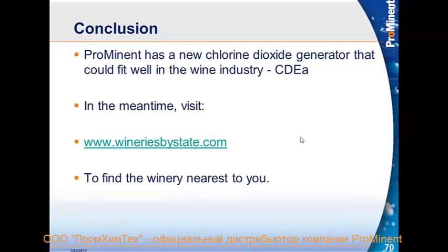You can make a solution and store it in a day tank as long as it's a weaker solution. You certainly couldn't put a 20,000 ppm solution into a tank because that will off gas. But a diluted solution will stay in solution for a couple of days, which you can use to meter off into your application at a smaller part per million concentration.